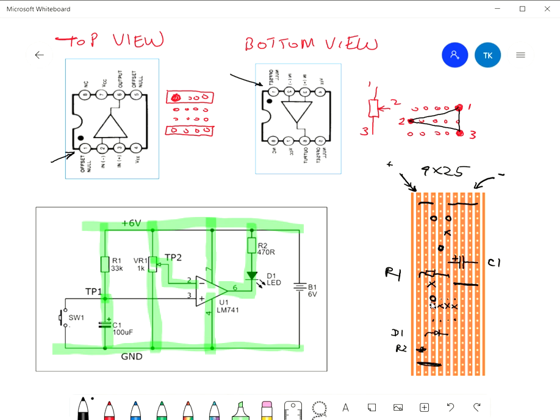Okay, looking back at our circuit, we've also made this connection, so we'll highlight it before we forget. So we've almost finished, except for switch 1. We're not using a real switch, we're just using 2 wires. Okay, and we have blue wires, let's say, which we will be using in the lab. So that one will be connecting to pin 3 of the IC, and the other wire will be to ground.